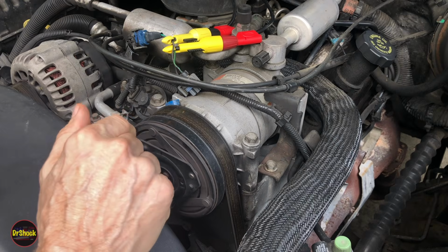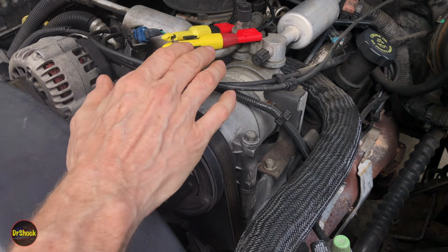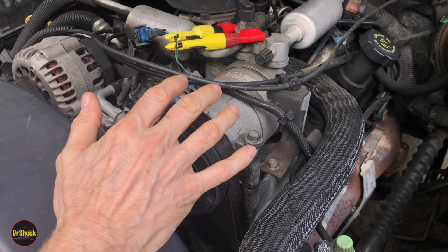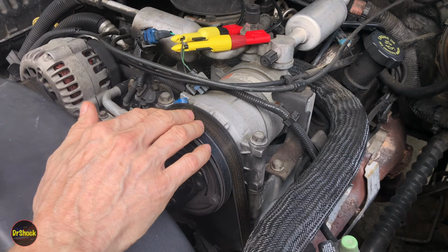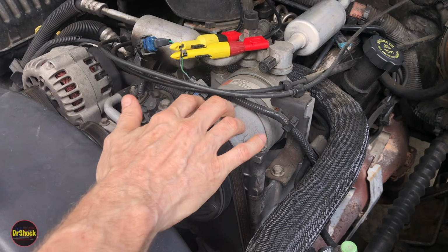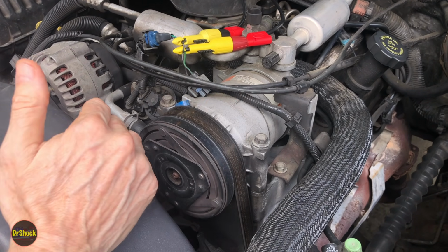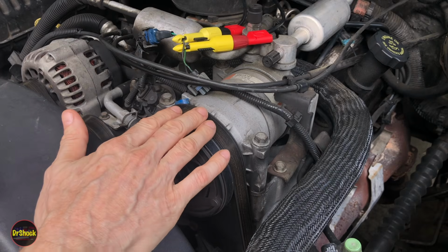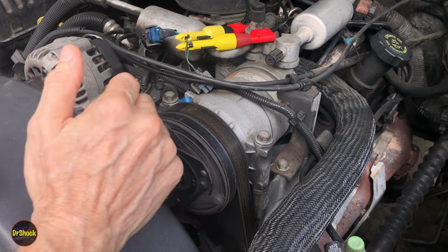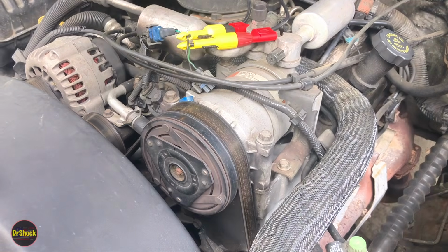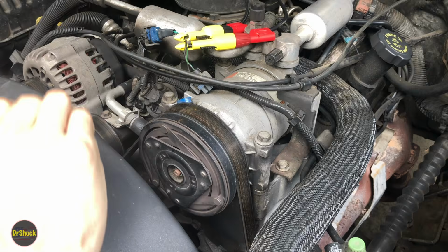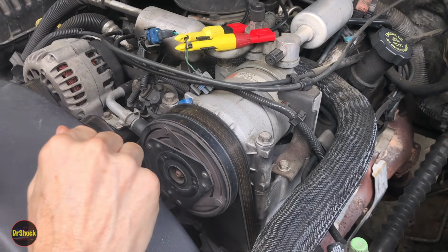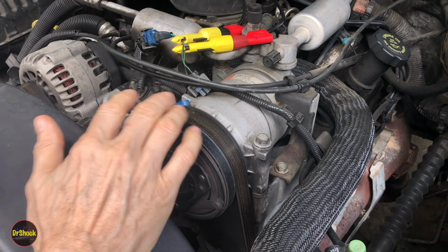My 2 cents on that is if you've got the black type from GM AC Delco and it's over 5 years old, just replace it. If you've got the new type, like this, and it's less than 10 years old, rebuild the clutch. If it's more than 10 years old, just replace it. You know, that's my advice. There's nothing in the GM service manual about this. It's just from decades of working on these types of vehicles. That would be my advice.